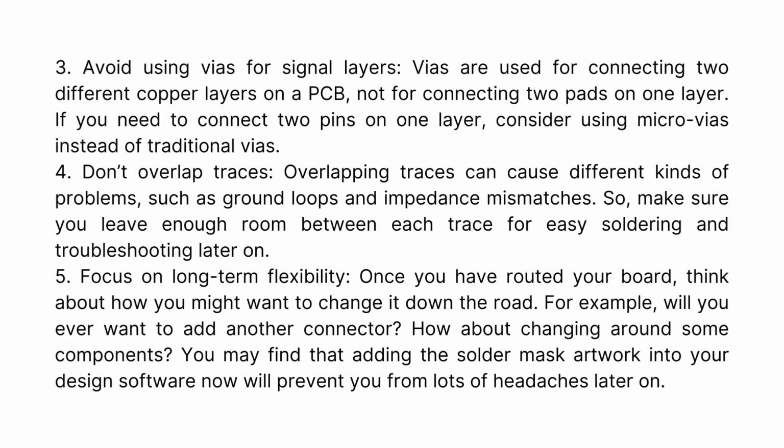3. Avoid using vias for signal layers. Vias are used for connecting two different copper layers on a PCB, not for connecting two pads on one layer. If you need to connect two pins on one layer, consider using microvias instead of traditional vias.